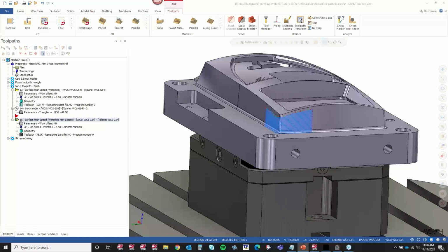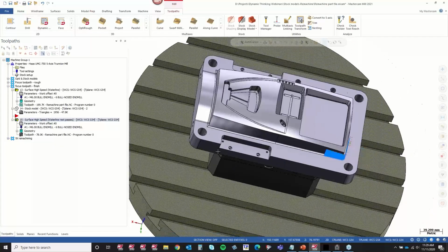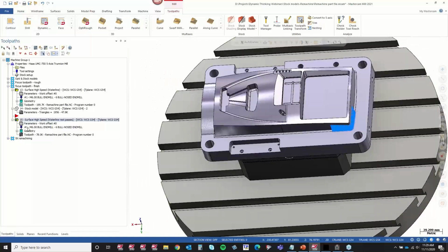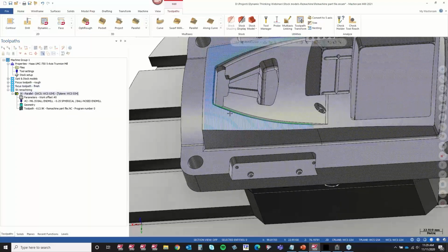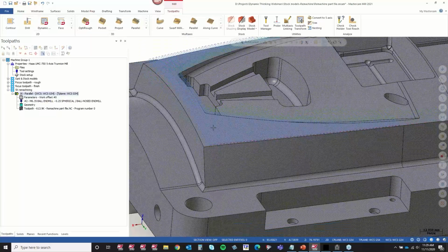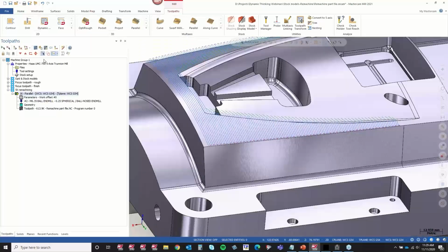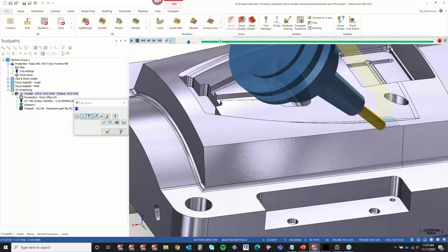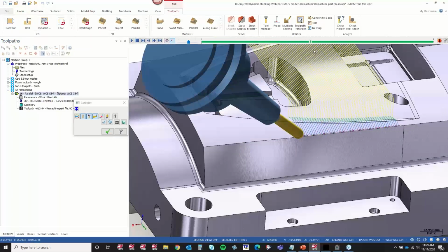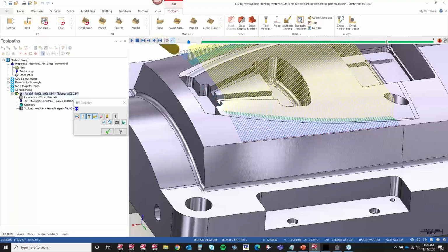So what can we do to fix that issue, right? And let's say that when we initially machined this part, it was done with a 5-axis parallel operation. So this was done on the surface, nothing too crazy, but it's just a simple 5-axis surfacing operation that comes across the part, right?